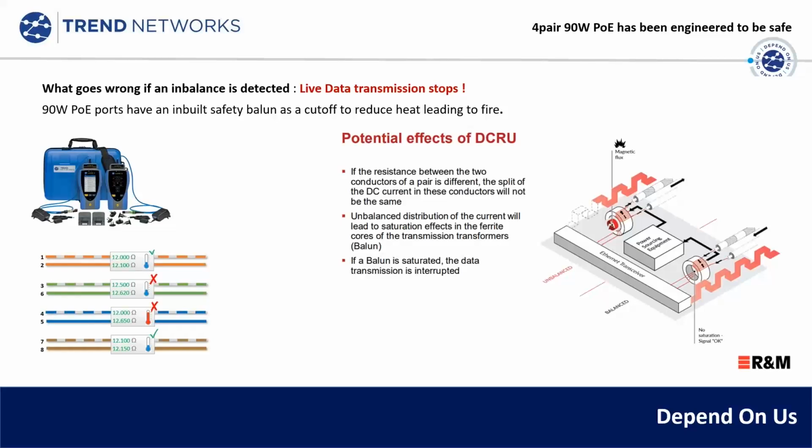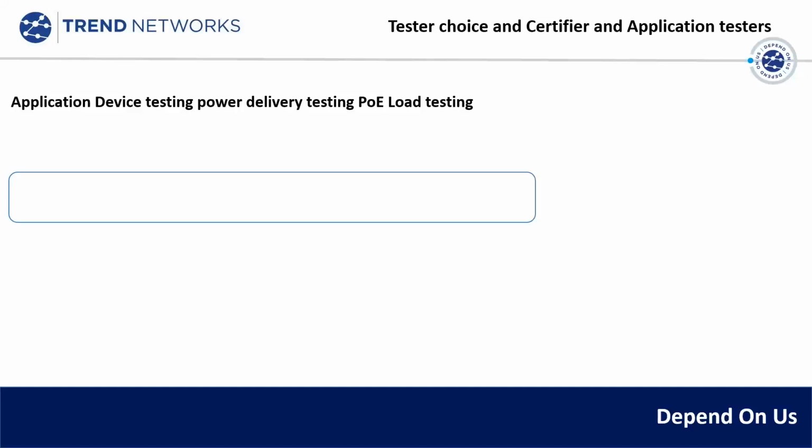So what I'm confirming here is if you don't do your resistance unbalance testing, you could potentially risk unreliability. As links get old or connections get warmer, if you're in a warmer environment, you risk it just stopping because it'll just cut out, okay, for safety. So certainly things won't burn down, but the safety mechanism is in there.